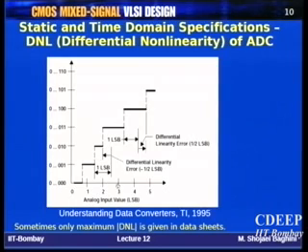So, for example, look here. This is the level corresponding exactly to this point, where the code goes from 001 to 010. This is the transition point. It doesn't matter whether it is shifted or not; you see there is offset also. In differential nonlinearity, we are not worried about the location of the first point.